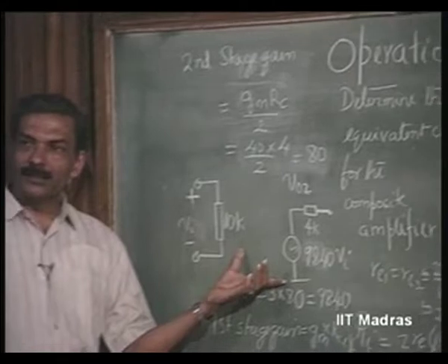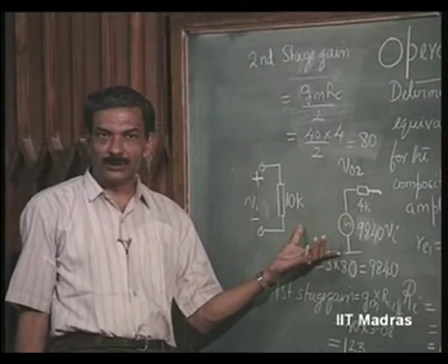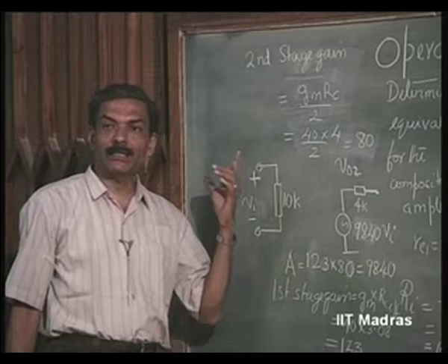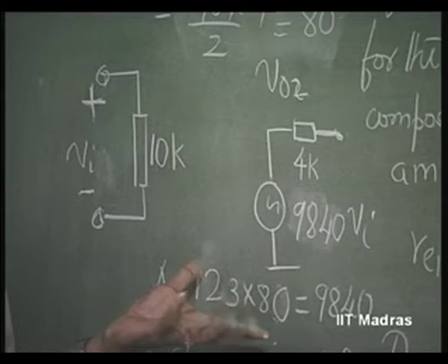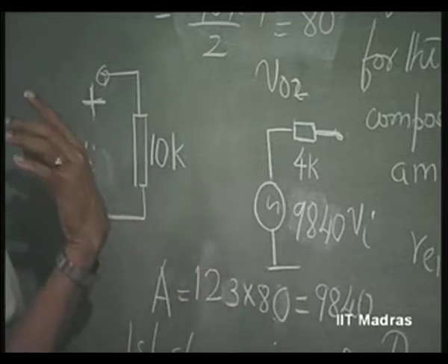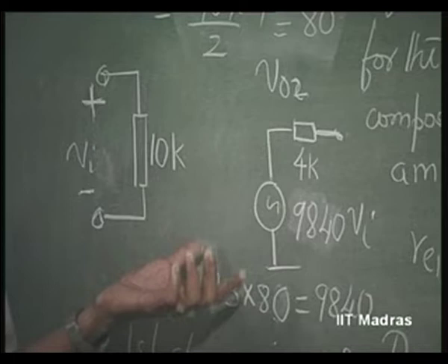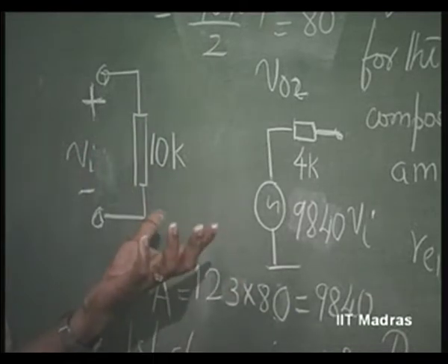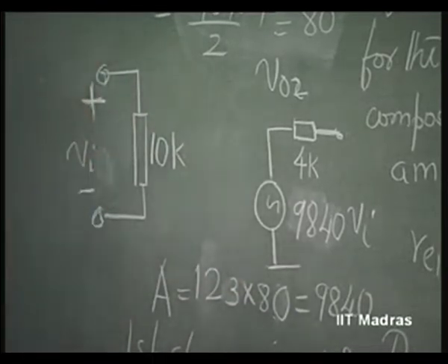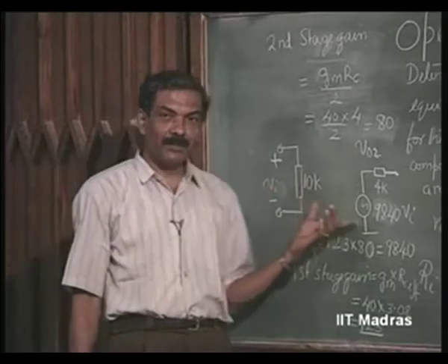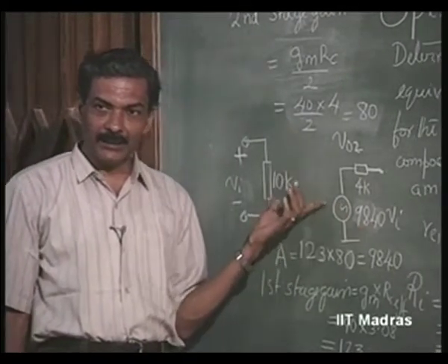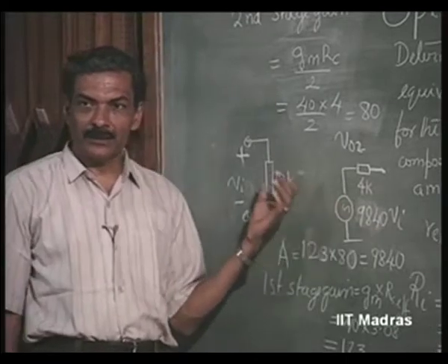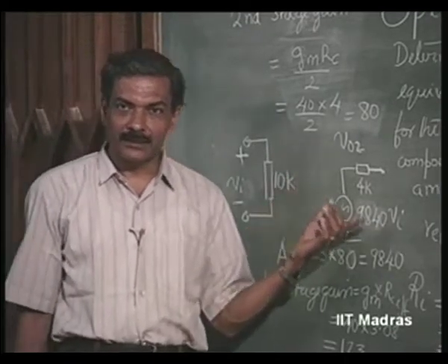Basically, it is a control source with a high forward transfer parameter. In this case, voltage gain. It could be current gain, it could be transfer resistance, it could be transfer impedance. Therefore, we have 4 types of operational amplifiers possible, depending upon whether the forward transfer parameter of interest is voltage gain, current gain, transfer conductance or transfer resistance.